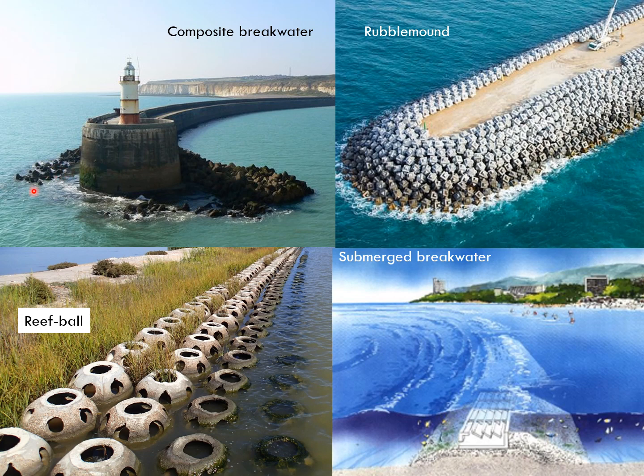However, we notice that in the head section here, there is no more rubble mound structure, possibly due to displacement after severe storm attack, whereby maintenance or repair work has not been carried out. It is common for breakwaters in the coastal region to be subjected to cyclic damage, and thus the need for